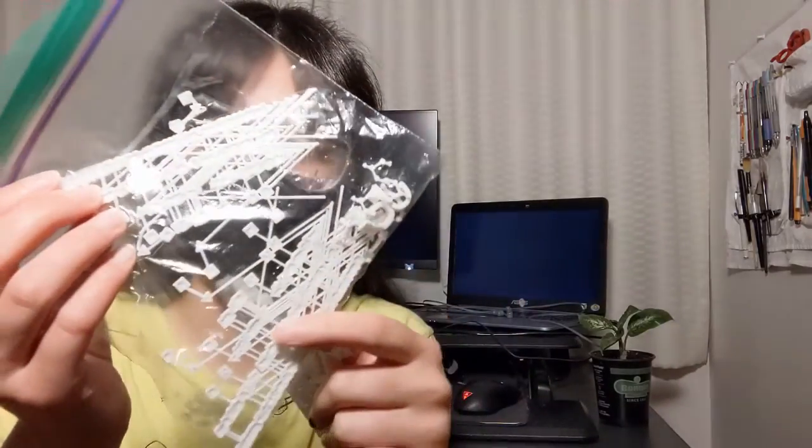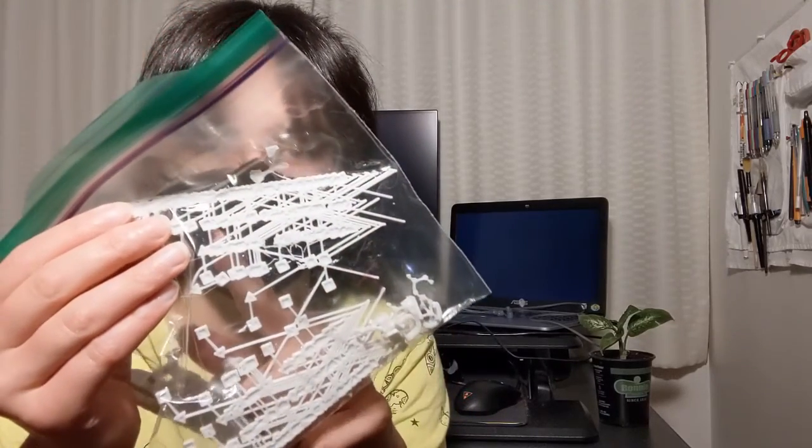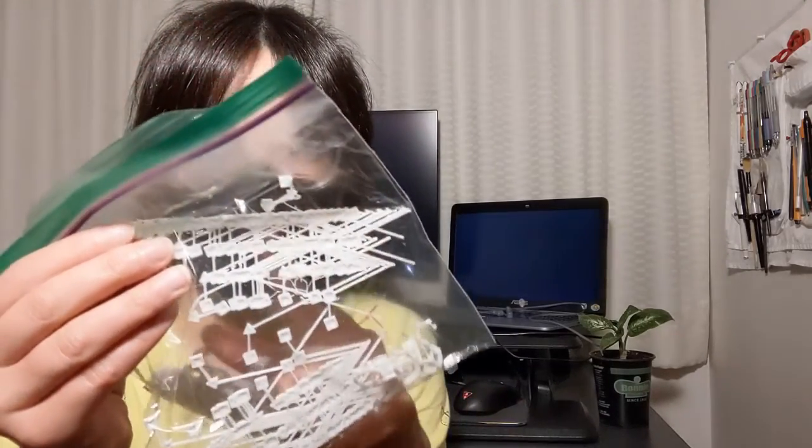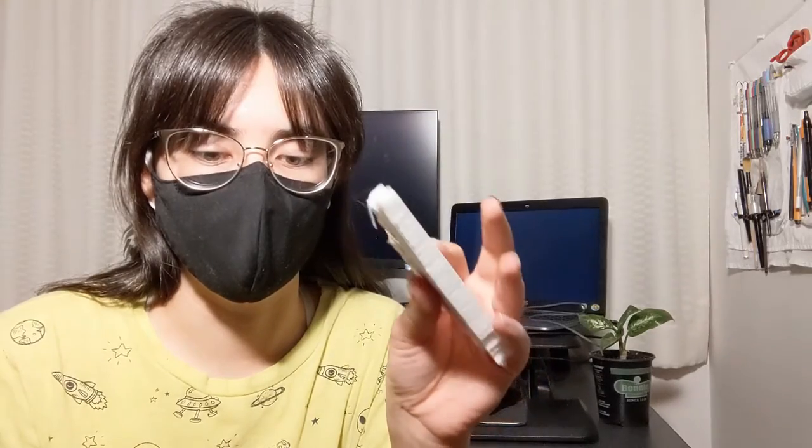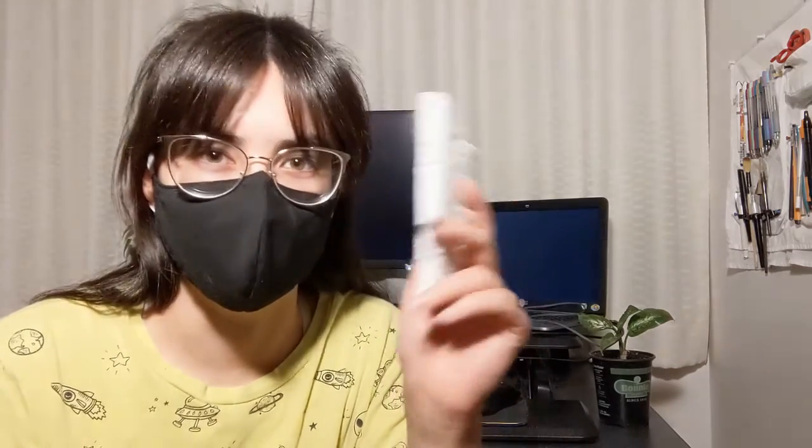This is actually from my 2nd attempt of trying to print just this specific piece. The first time it printed a few layers down and there were just disconnected pieces. It just really wasn't adhering at all, so I tried to re-level the bed, recoat the bed in glue, and I got a slightly better result, but still not all that good. And the 4th piece that's remaining is one of the pieces that's supposed to take over a day to finish printing, so it's not going to be done by the time I finish editing this video, so I won't be able to make it into anything really cool until much later.